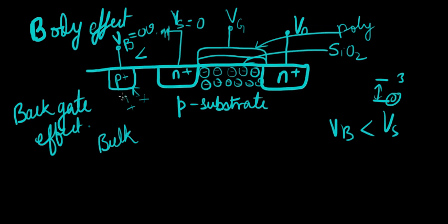Because holes are attracted to negative charge, or negative potential, so they start moving there. But where do these holes come from? They come from here, or anywhere in the device basically. But what does that mean? When you have holes going towards this terminal, or that region, you're going to be left with more negative ions around here. You're going to have another layer, maybe, of negative ions. In fact, it's a bit more.